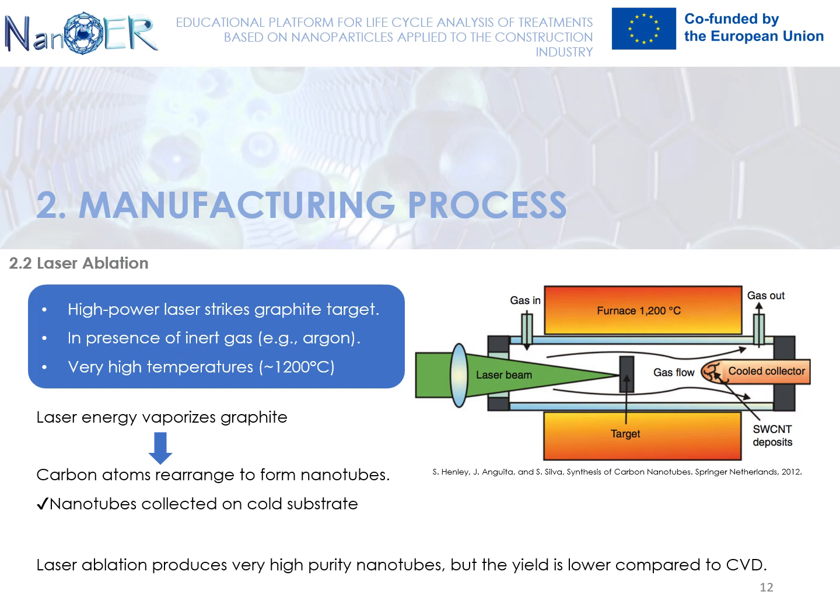The temperature level plays an important role in the quality and yield of these products. The ideal temperature is 1200 degrees Celsius. If a lower temperature is applied, the CNTs show lots of defects. The production of single-wall nanotubes is performed by incorporation of small quantities of transition metals, nickel or cobalt, into the graphite pellet as catalysts. The yield of single-wall nanotubes depends mainly on the metal catalyst used.